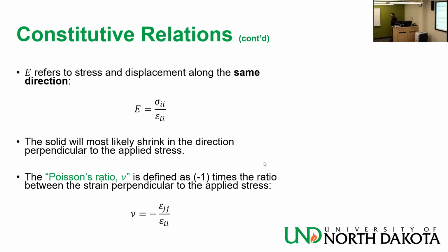Okay, now let's see. For the rocks, the Poisson's ratio will vary from 0.4 to 0.1 ish. 0.4 is a little bit high. 0.1 is not impossible. Your TA Kalu is doing experiments in the lab using transparent gelatin blocks, and those get close to 0.5. Get close, not exactly, like 0.47, something like that. You get close to 0.5, but you cannot go over 0.5.